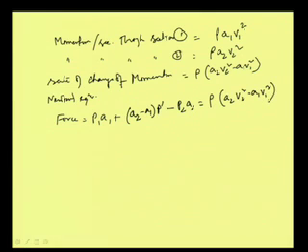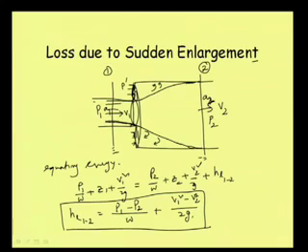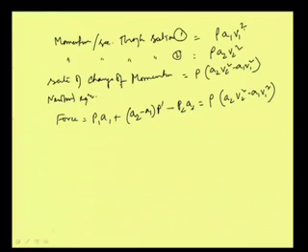And as the fluid at the corner is at rest, the pressure at this point can be considered almost equal to the pressure just upstream. Although we are drawing it far apart, this P1 is the pressure here. So, as this fluid is at rest and in contact, we can consider this pressure and that pressure, that is P1 and P dash, to be almost equal.